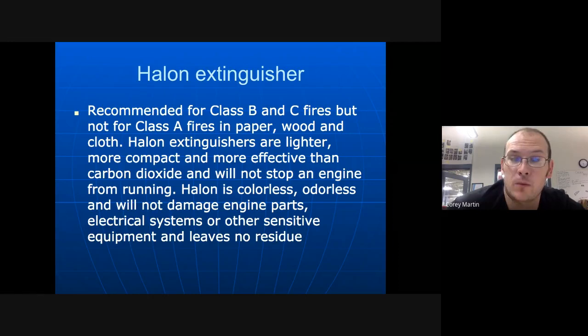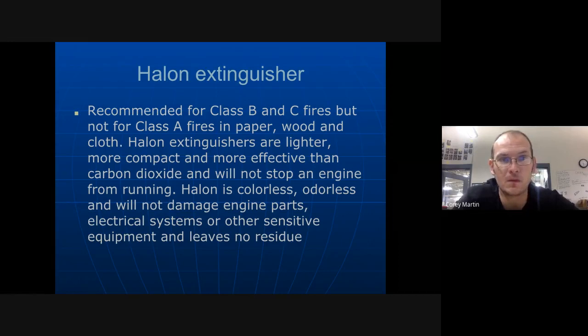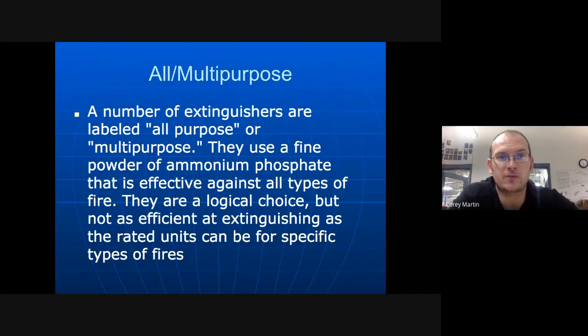This is also what most restaurants will have. You can't have a water-based system on top of a stove or on top of a big grill because if there's grease there, it's going to get worse. So a lot of places will have a halon extinguishing system. A number of extinguishers are labeled multi-purpose, and we already talked about that just a minute ago. That's along the same lines as that dry chemical. And you can look at the picture or the pictogram on the fire extinguisher so that you can actually see it.